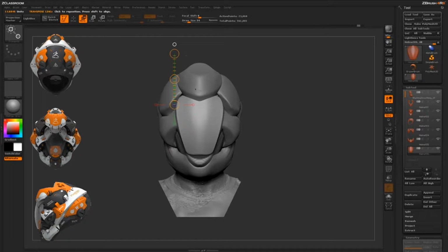Another thing to note is this white circle right here. This white circle is extremely beneficial if you want to draw straight lines on your model. So if you want to come in and say draw a straight line from here to here, if you're going to do it normally, you'd go back to your draw option, and then let's get the standard brush here, and you try to just draw a straight line. So you come up here and you just draw a straight line. So that's pretty straight, but it's not as perfect as it could be.